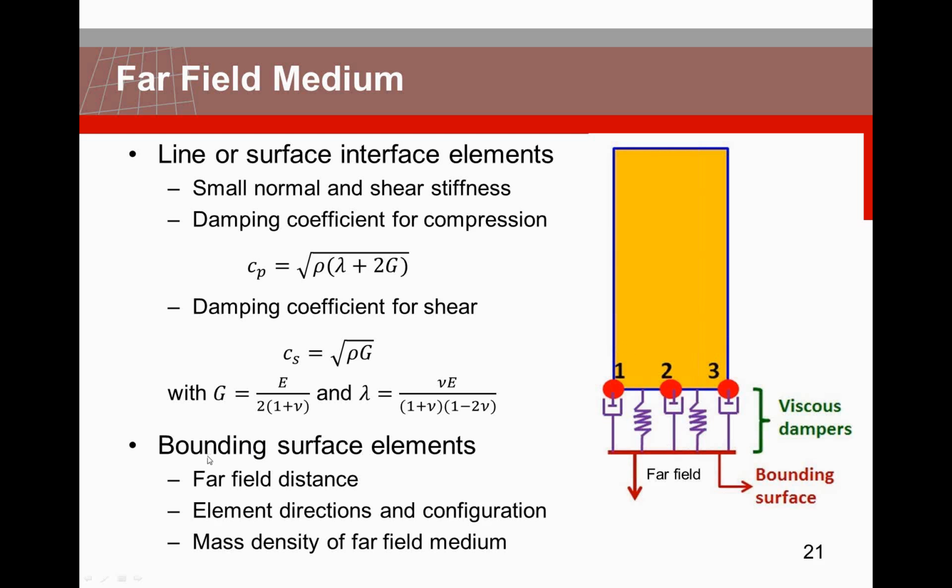What's more interesting here to say that you give a certain distance here to the far field, you give your directions and the configuration, and you give the mass density of the far field. So in case that, say, your sand is here connected to a more rock type material, you can adjust that here in the mass density for the far field medium.